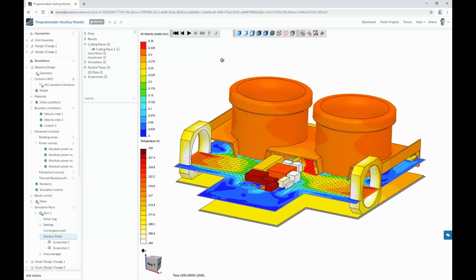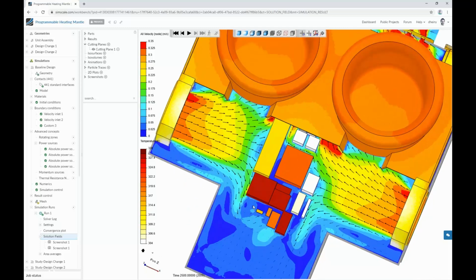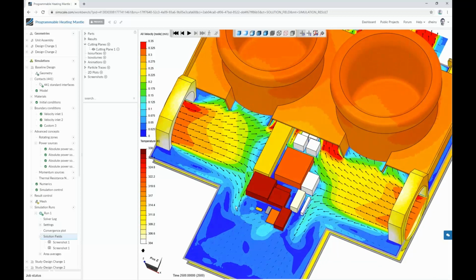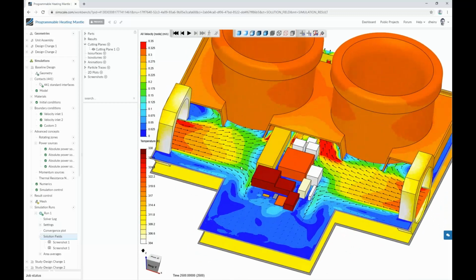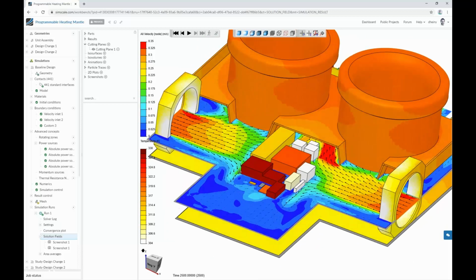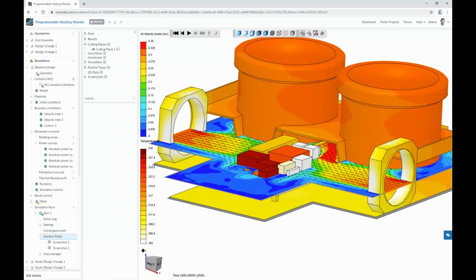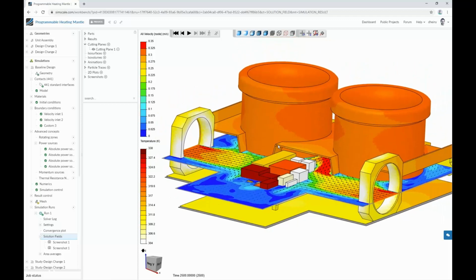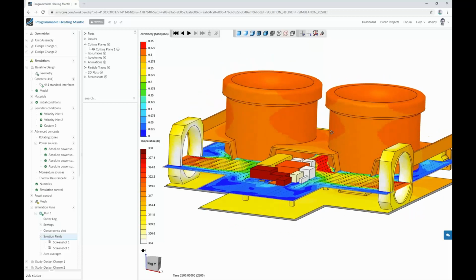And one thing that gets obvious here is that we have a problem with airflow coming through here. That's the velocity, right? The red part is 0.35. The blue part is essentially no air moving, right? And we can see that the air is not going sufficiently well around that corner and not hitting this component over here enough. I don't want to overdo it. If we would add more slices, we would also see that the baskets aren't well cooled above this sheet metal part here, right? So that's why we tested cutouts here. We're going to see that in a second.